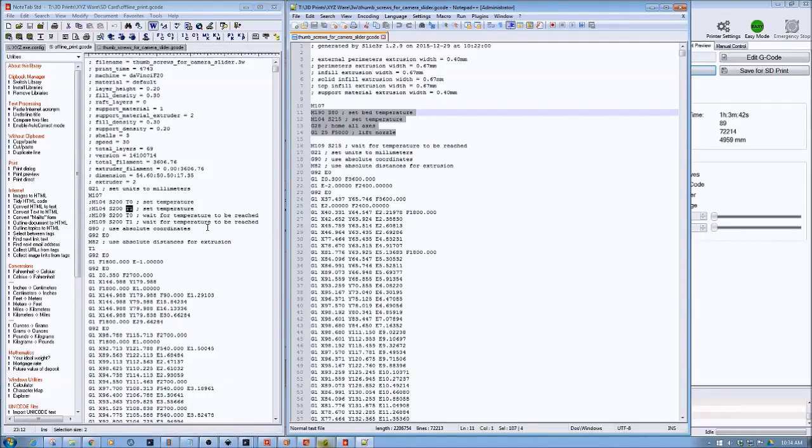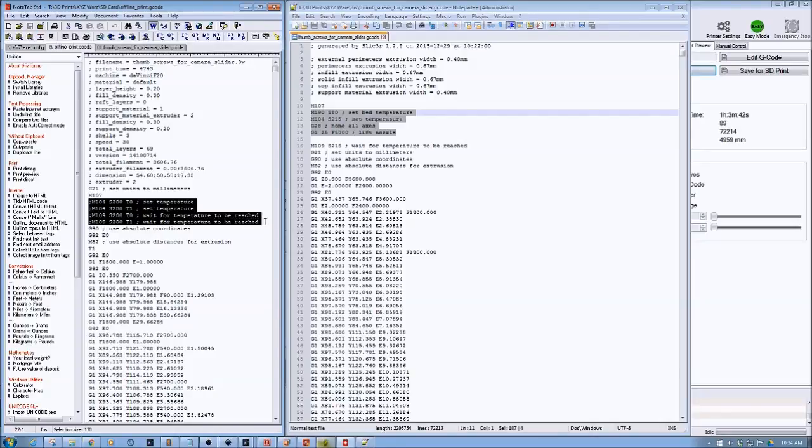However, from reading internet posts, you're not able to force a temperature setting in G-code higher than its basic, intrinsic temperature on the cartridge itself. Apparently somehow it reads that, and I think this is one reason this is commented out with the semicolons. I think somehow XYZware uses these comments. I'm not sure why it would transfer these to the G-code unless there's some sort of checksum between these. I haven't been able to do a base64 decode of the file, so this is coming off the cart, and this is the only way I'm getting it.